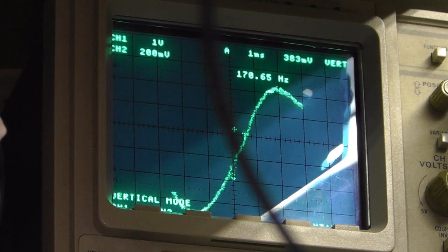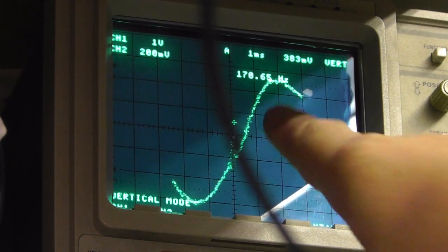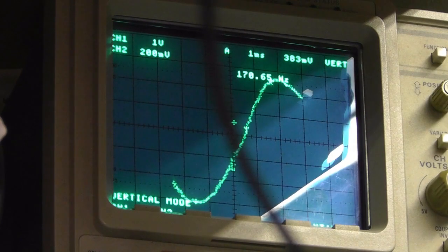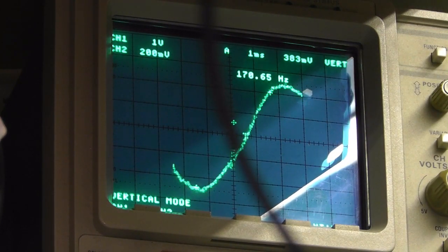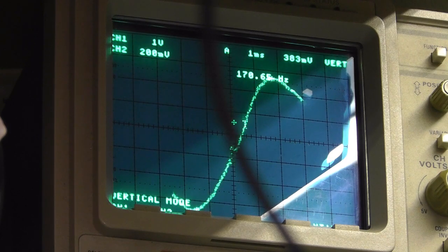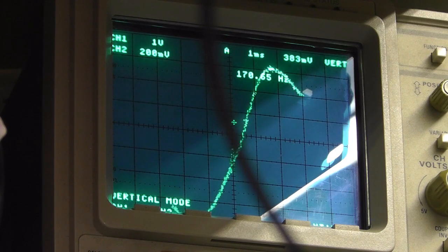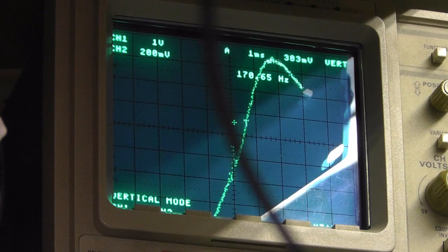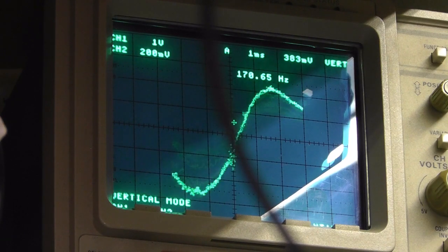Let's bring this up a bit. There we go. There's the S. It's looking a lot better already, actually. We try and get a bit of amplitude back. Obviously, we want amplitude because that's our sensitivity, but we also want a nice linear S. Okay, we're really peaking that up a bit now. Let's turn the volume down a bit more. Let's turn the RF gain down from the Wobbulator.